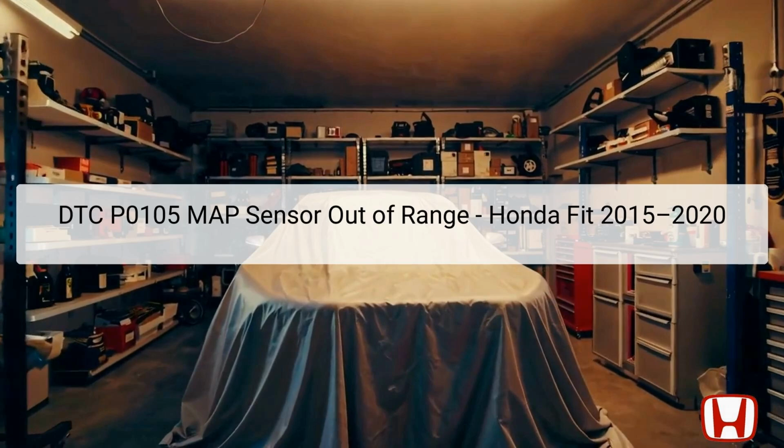The Diagnostic Trouble Code, or DTC P0105, indicates a malfunction of the manifold absolute pressure MAP sensor in the Honda Fit models from 2015 to 2020. The MAP sensor plays a crucial role in monitoring the engine's air intake pressure, which is vital for the Engine Control Module, ECM, to calculate the optimal air-fuel mixture for combustion.